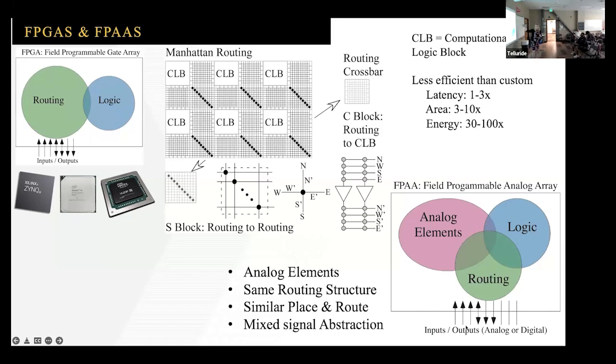It also very clearly, by the way, on the digital side, if you do it this way, they know that this then scales not order n squared, but order n. And that's helping with tiling things. So to assess that, the metrics that make sense are everything that has to do with ops and watts and millimeter squared. That's really what matters, because we can make a ripple-carry analog multiplier, as opposed to carrying on with a long multiplier, but the carry, that's where the energy goes.